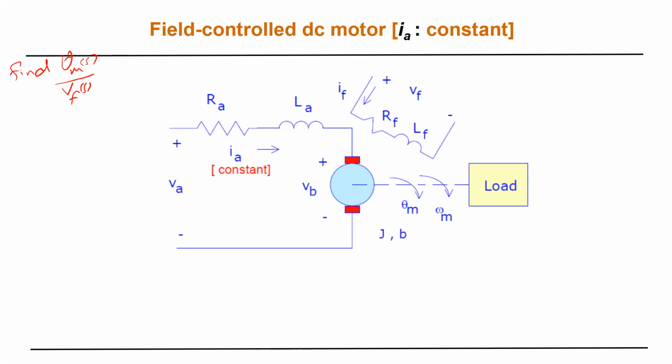No, not short circuit. You are keeping it constant. Just constant DC current. The idea in the inductor, if it's a constant current, so the L di/dt will be 0, right? Yes, but don't forget, you have rotation also. You are producing a certain Vb, because the system will work with a certain rotation as well. I see. Okay, but it is not 0. It's constant.